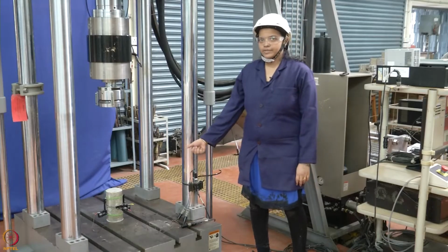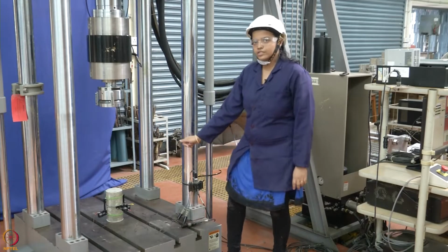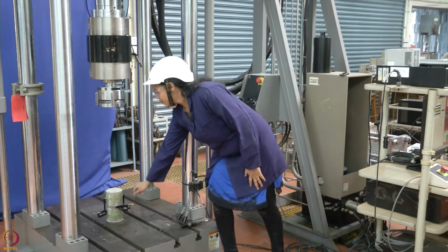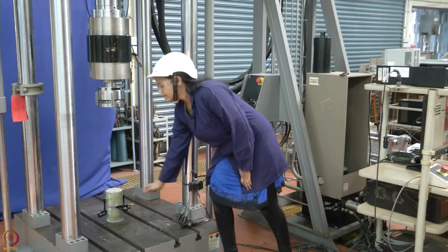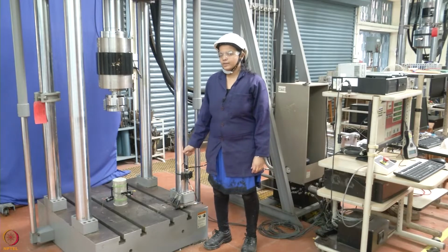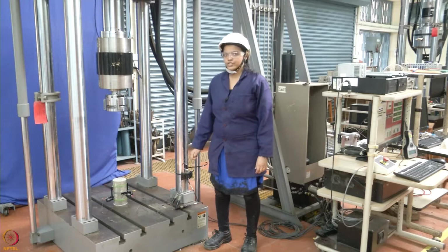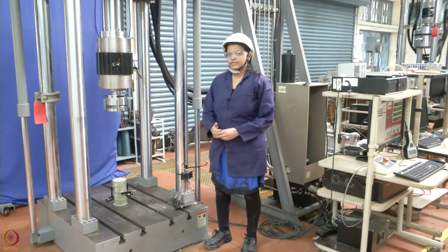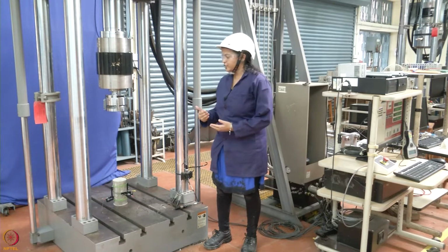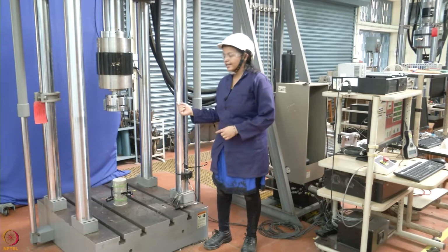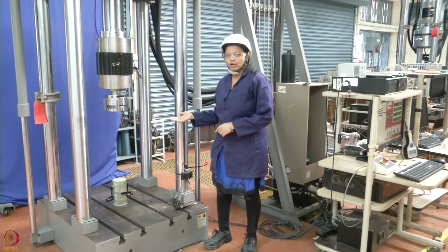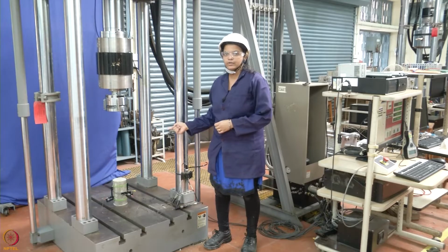Now the testing setup is ready. The circumferential strain is going to be measured by this extensometer, and the axial deformation is going to be measured by these two extensometers. In this test, we will control the testing by means of the circumferential control. This is done because the circumference is going to always expand, whereas the axial deformation will always compress. But what happens is, if there is a crack occurring near the extensometer, it might slip off. That is why we are using this circumferential control in this testing.